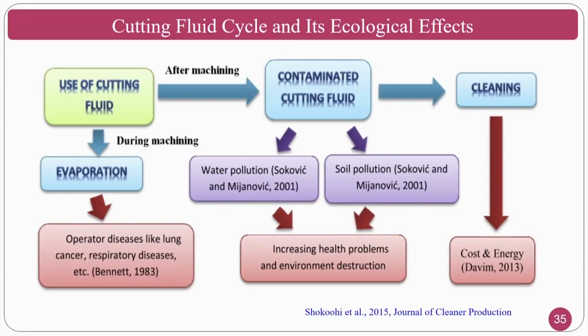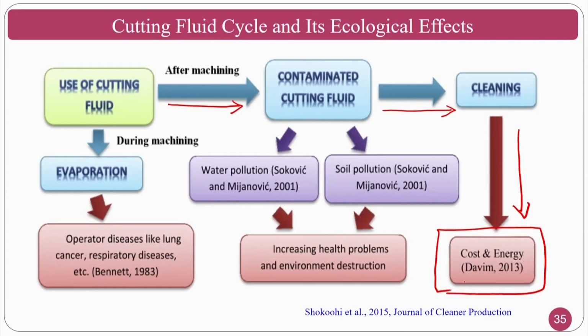Use of cutting fluid after machining, what will happen? The contaminated cutting fluid will come. Contaminated cutting fluid means it is thermally cracked and has lost its original potential; the original potential is slightly decreased. Then there are multiple options. One is cleaning before recycling, but it incurs a lot of cost and energy.